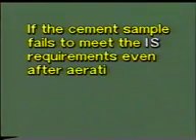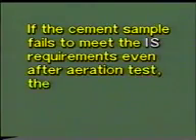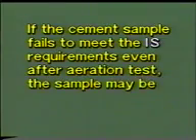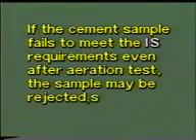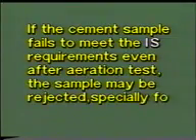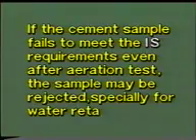If the cement sample fails to meet the BIS requirements even after aeration test, the sample may be rejected, especially for water retaining structures.